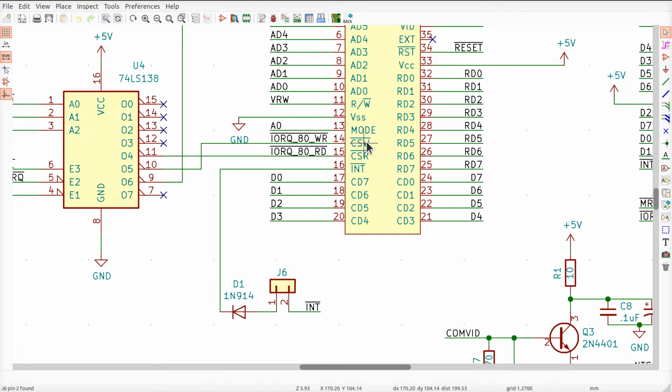Okay. In other words, it vectors directly to the handler for this chip. So you don't have to play the "is this the why I'm here? Is that why I'm there?" and so on in your interrupt handler, which, as anyone who's actually had to suffer through all this before would know, is a waste of time. It creates a lot of latency in your interrupt handlers.